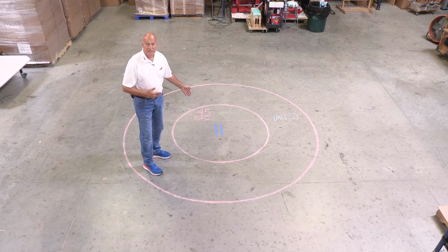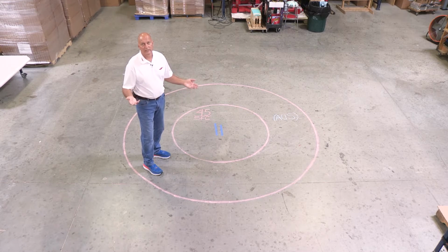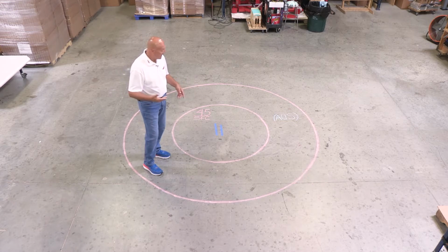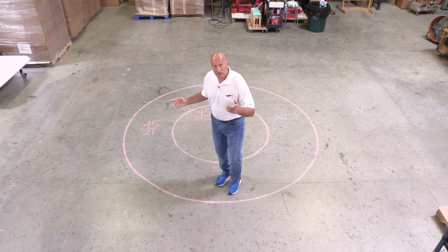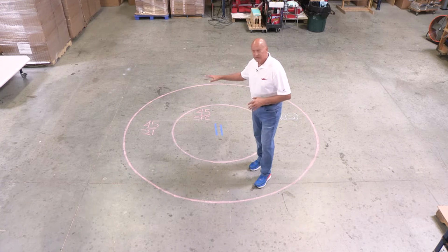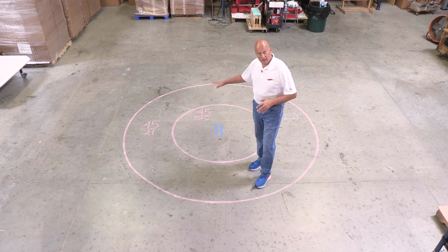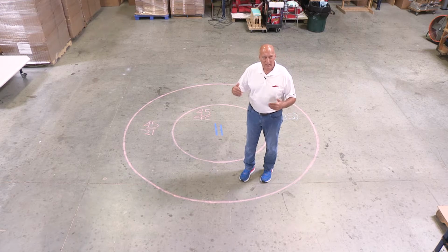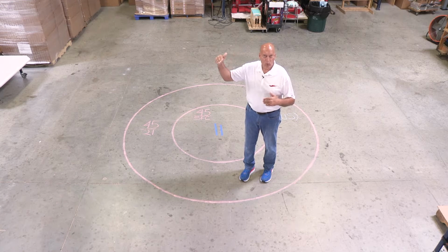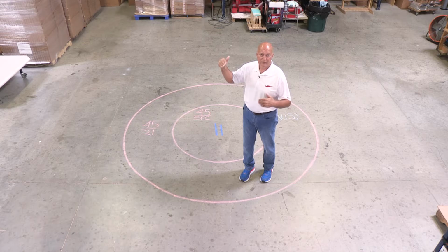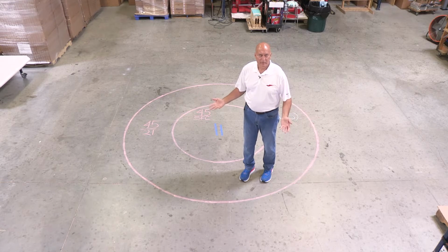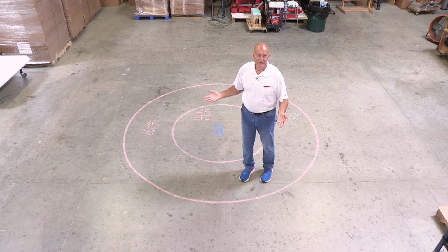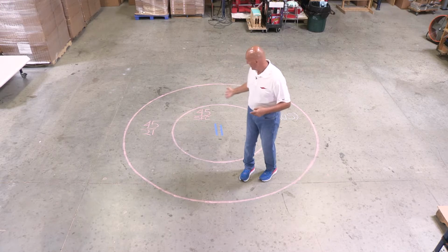Also, I have taped the runways on the floor, the runway configuration you would see if you looked at a sectional map of KAUS. I've also drawn the altitude parameters. Remember, Class Charlie airspace normally tops out about 4,000 feet AGL. Austin Bergstrom International Airport is about 500 feet MSL, so that makes sense here.